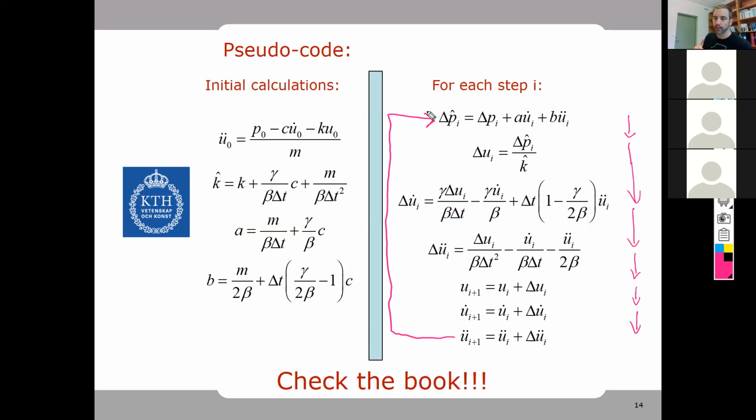And thus, every time we do a new calculation, we'll generate a new value for this. So as you can see, this method is slightly more complex than the previous one. It involves slightly more steps, and that is a characteristic of implicit methods that are normally a little bit more complicated, a little bit more time-consuming for the computer.